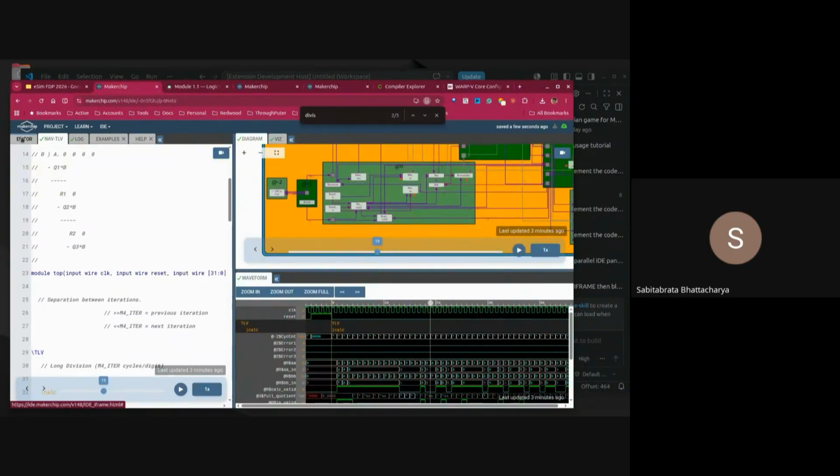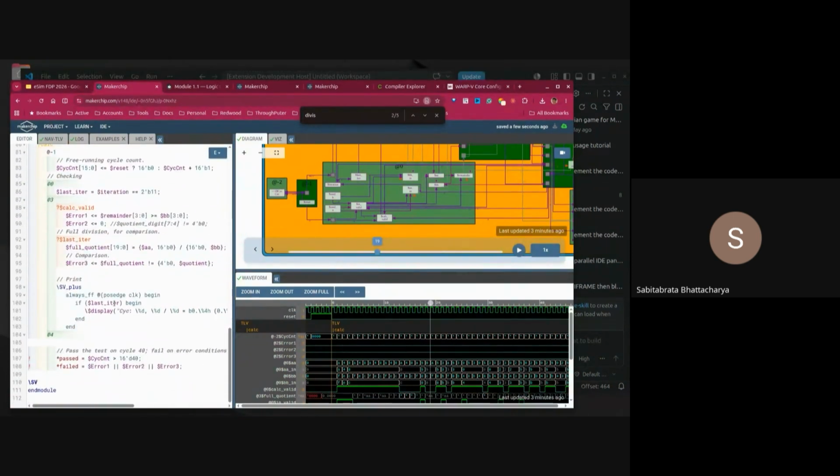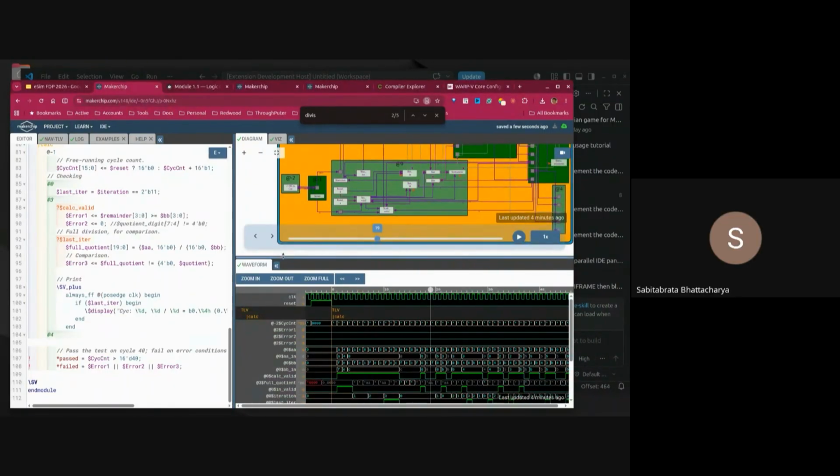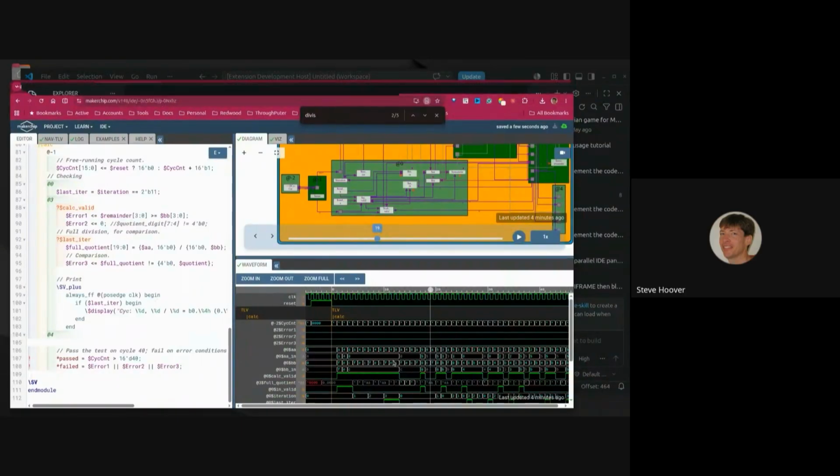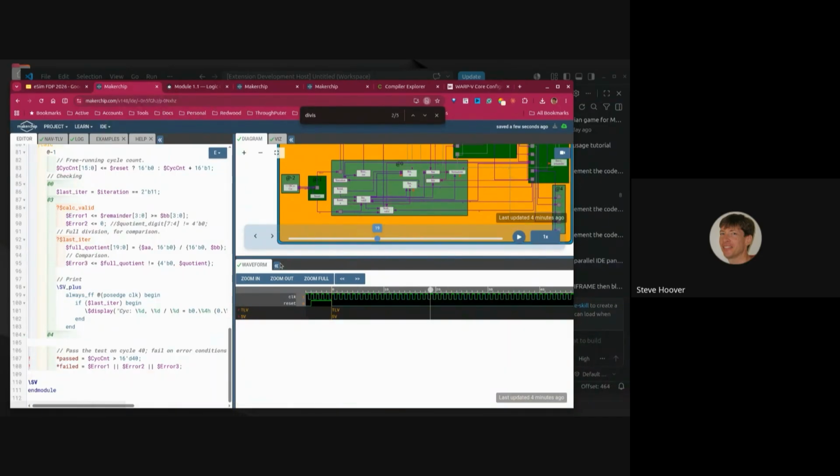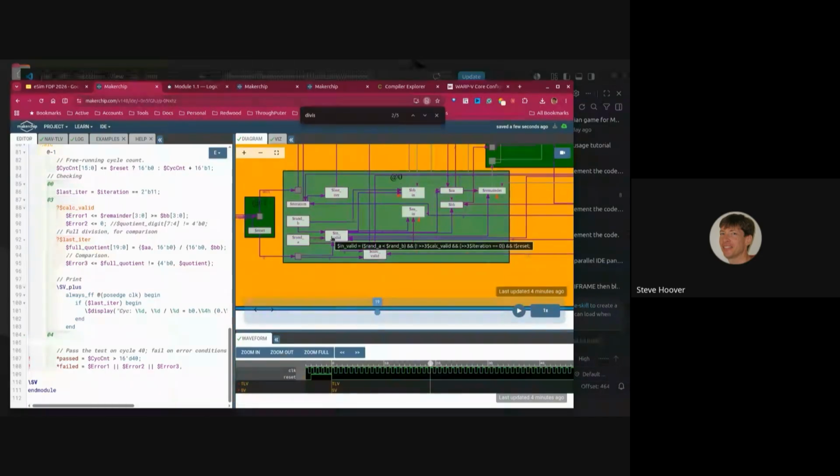If I can show the visualization to my students, like if I can put a project in and visualize it easily, like what you are showing. I am not showing complicated structures, just simple models only. Just simple things, in which there is no CDC concept. I'm not going to SoC level, just a simple block. Right. Yeah, so the waveform viewer absolutely works with Verilog simulation. The diagram does not. The diagram is representing your TL-Verilog constructs, your TL-Verilog circuit. So you won't get this logic diagram specifically.